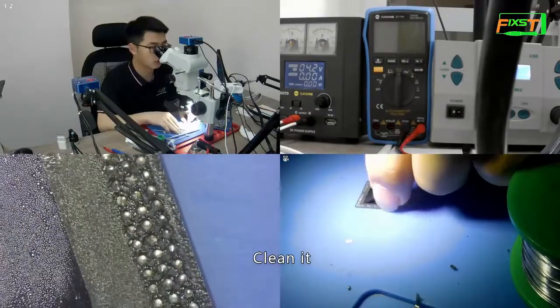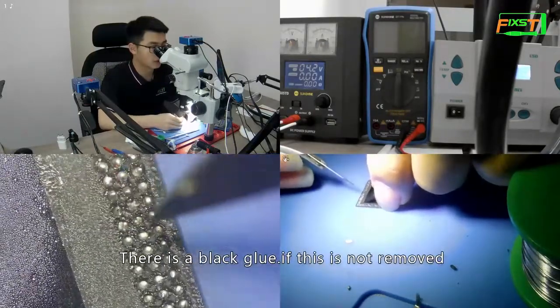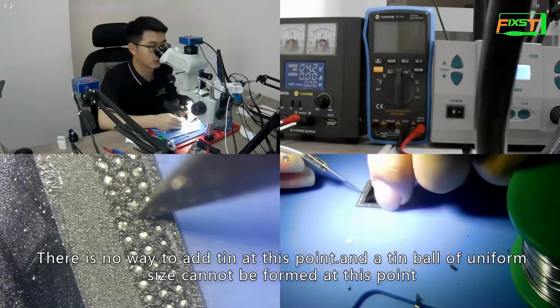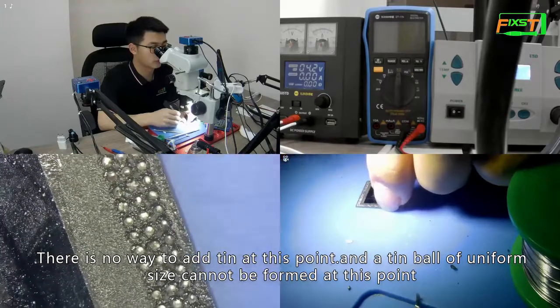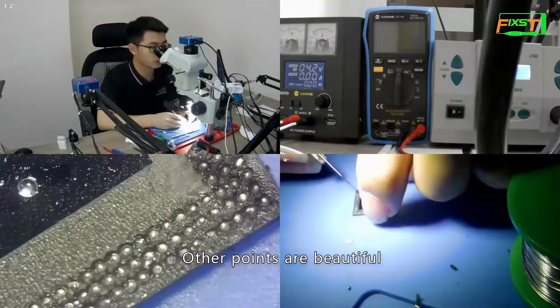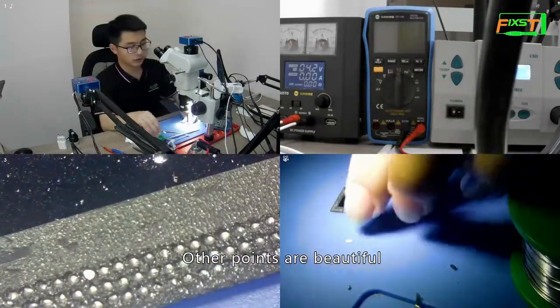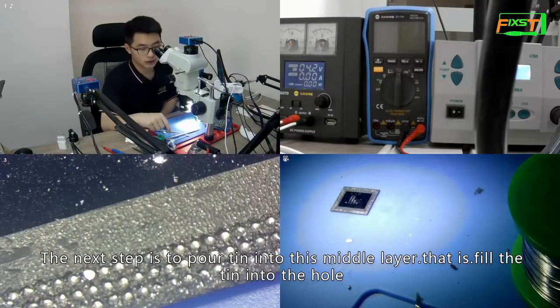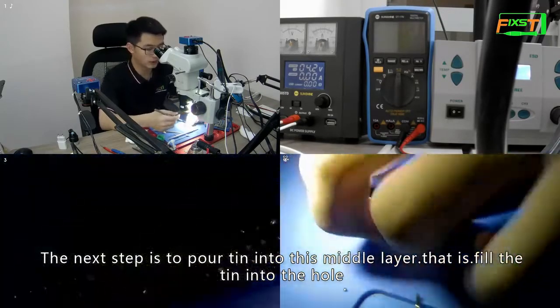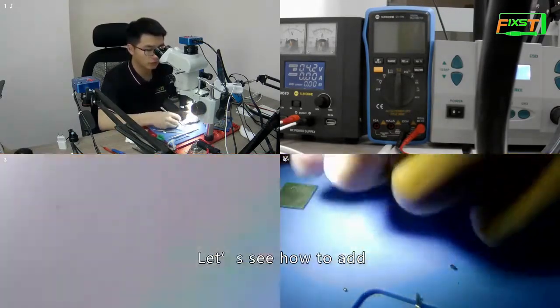Clean it. There is black glue. If this is not removed, there is no way to add tin at this point, and a tin ball of uniform size cannot be formed here. Other points are beautiful. The next step is to pour tin into this middle layer. That's it. Fill the tin into the hole. Let's see how to add.